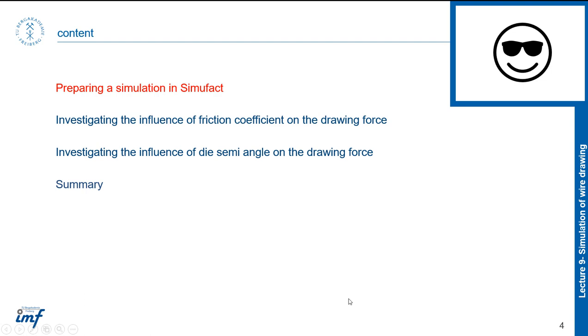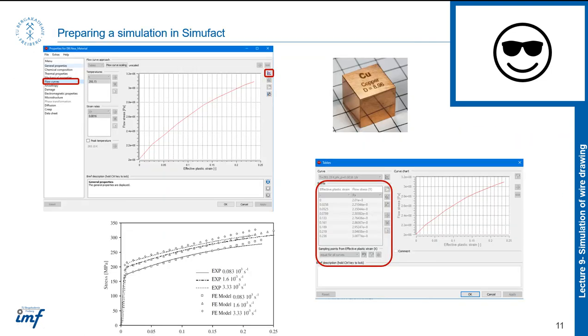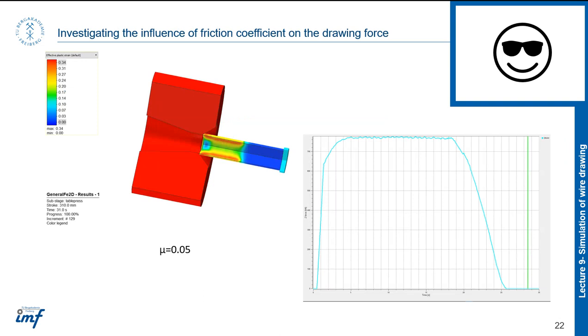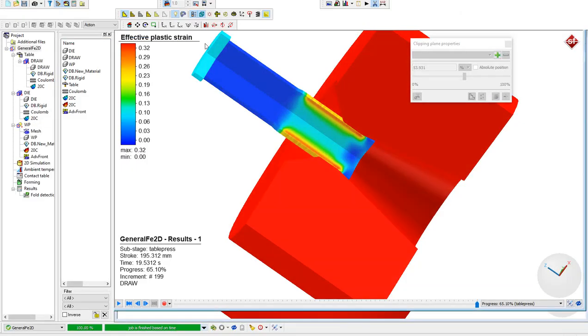So we finished the first section. Now, in the way I explained, I have prepared and run some other simulations by changing the coefficient of friction, the Coulomb friction. Our simulation is running with mu equal to 0, then I save the result, then I rerun it with mu equal to 0.05 and then mu 0.1. In the output, if I go back to the result here, there is an option here.